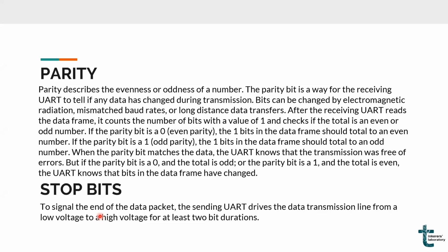And then there can be an Ethernet module and a Wi-Fi module. These modules can be integrated into the microcontroller unit or the microprocessor unit using the UART interface. Also, a GPS module is connected with the RX pin. The GPS module, as apparent from the name, does global positioning of the device. And a GSM module can also be connected with this same UART data transmission line.